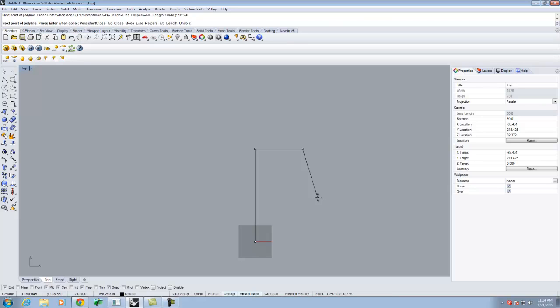The coordinates we're typing right now are called absolute coordinates. It means in the overall plane of things, this is where these points exist in coordinates. Sometimes you don't really know where a particular point is going to be, or it's too hard to calculate where that point would be in its absolute coordinate system. So we can instead use something called relative coordinates.